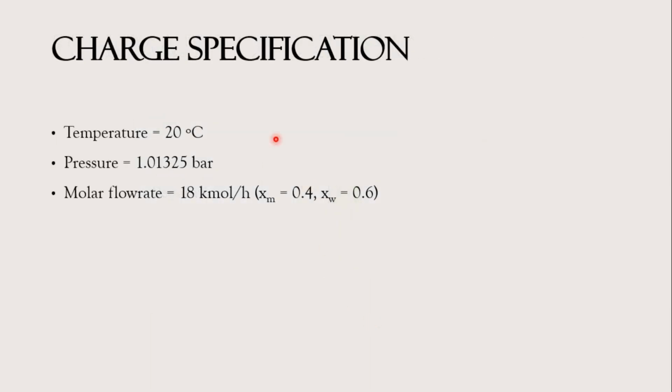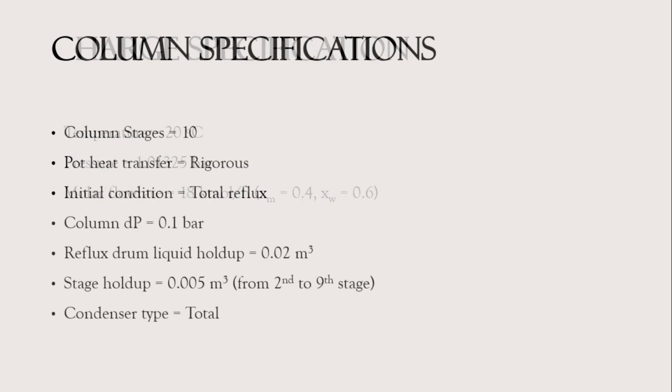So we have been given the charge specification: the charge which is fed to the column is at a temperature of 20 degrees centigrade, a pressure of 1.01325 bar, and a molar flow rate of 18 kmol per hour, with a mole fraction of methanol of 0.4 and that of water of 0.6.